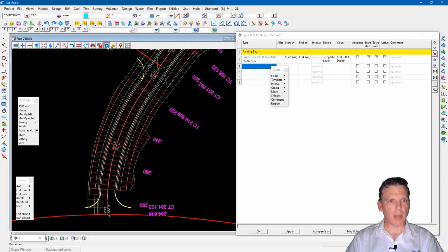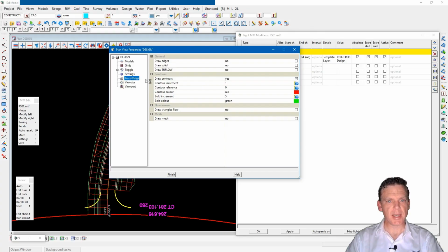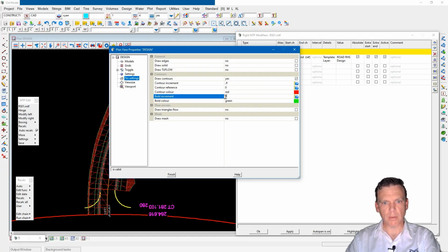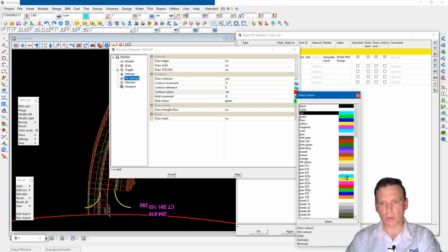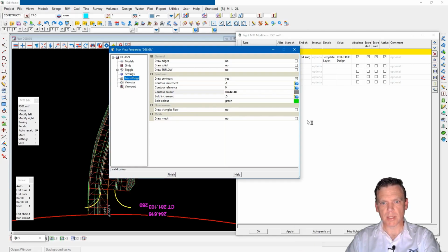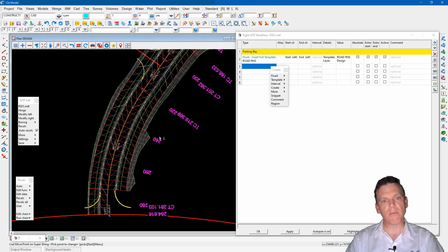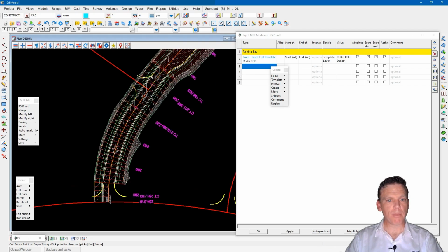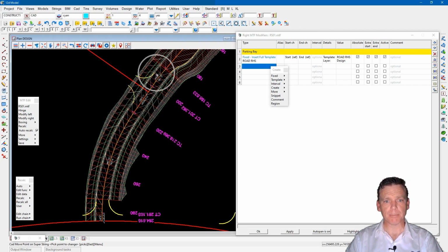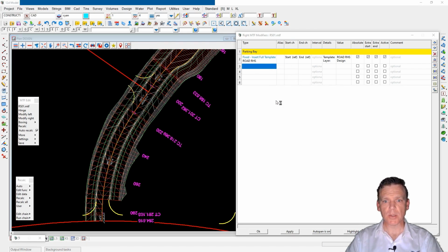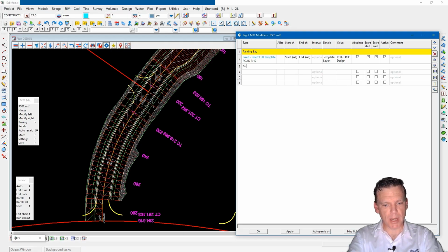and change the interval up. So that's under the tin settings here, where we might make that every 0.1 and 0.5. Or we might also change the colors to sort of a dark gray and a lighter gray there for every fifth contour line. You can see the V shape there of the center line. So we'll be producing that into a one-way crossfall, maybe back from the tangent point here. So let's insert comment, super elevation.